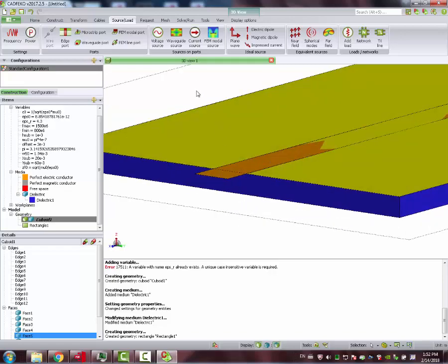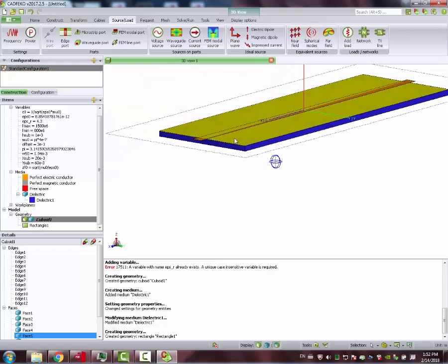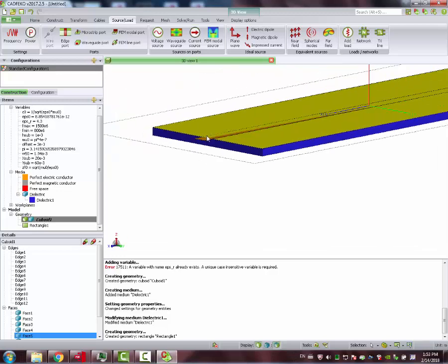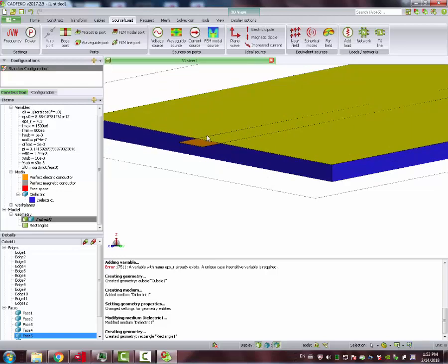Well, you can write down the dimensions, etc. It's doable, you can do it that way, but it's easier using the pick tools of FEKO. By pick tools, you just press Shift and Control at the same time. And as you can see, as I'm moving my mouse here, all these pick points are available without the need to compute them manually.